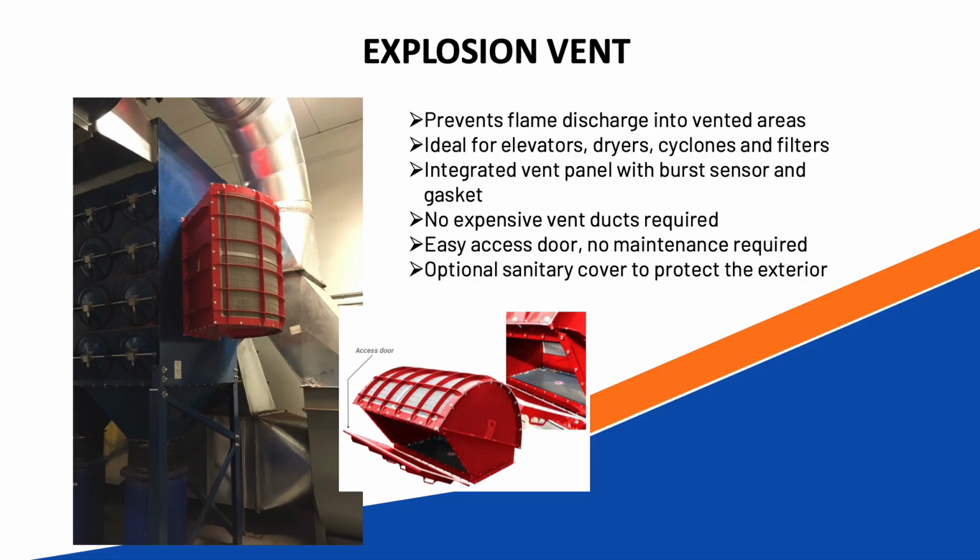And basically, on the other side of that flameless vent, all you're going to get is smoke and cloud. We can use these with elevators, dryers, cyclones, filters, whatever type of vessel that you're trying to protect. And we do all the calculations in-house as well.